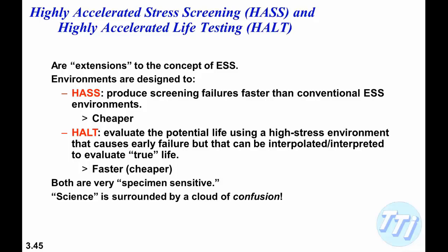Okay, extending from that, it would be really cool if we could come up with a testing system that could do accelerated testing. If we do a random test, for instance, at a particular level and find that our specimen survives, can we increase the random level and see how long the specimen survives, and so reduce the length of testing that we have to do?